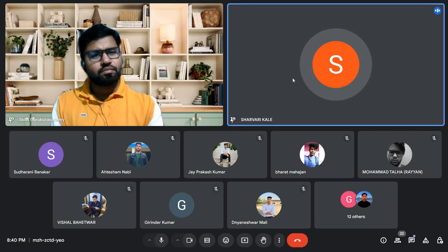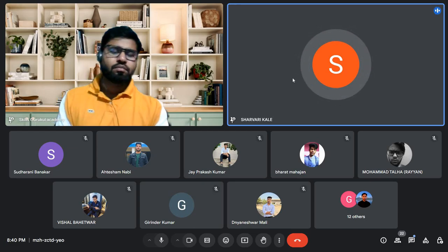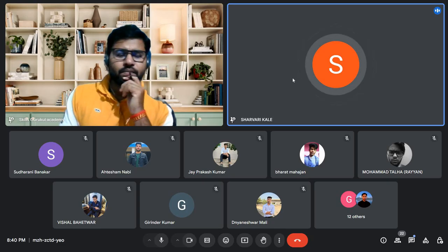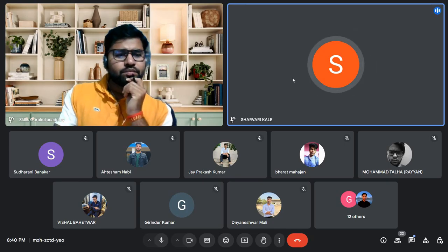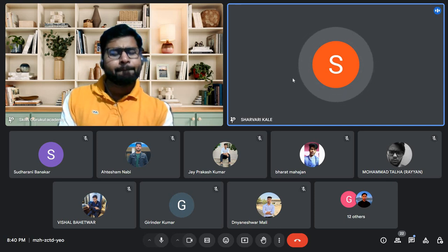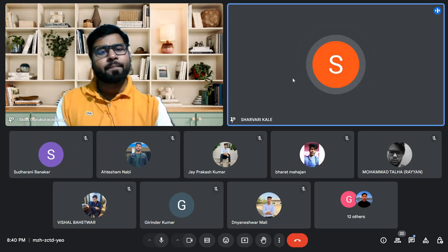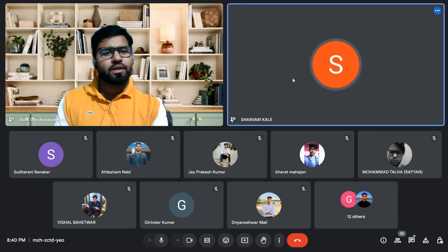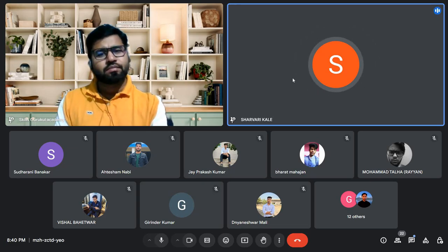In CAD to BIM, we insert CAD files in Revit, and we make models through that. In scan to BIM, we scan some buildings and their pictures, and from that file, we make a plan.